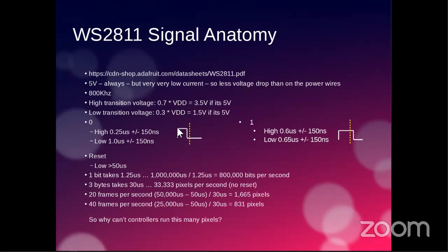It then has a timer, which is probably something like a capacitor, and it waits a certain period of time. At that point, it reads the signal, and whether it's low or high when it reads the signal, it's either reading a 1 or a 0. So this becomes really important, because when the signal is a nice clean shape like this, you can see how these are nice and easily read.